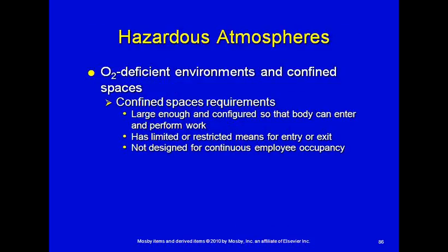O2 deficient environments and confined spaces are hazardous atmospheres as well. Confined space requirements. Confined spaces have to be large enough in order to get a body into them to perform work. So there are tunnels, there are crawl spaces, whatever you want to call them. They're confined, but they're large enough that you can get a body in there to work on whatever it is that's in there. But when you get in there, you have a limited and restricted means of entry or exit. It is not designed for continuous occupancy.